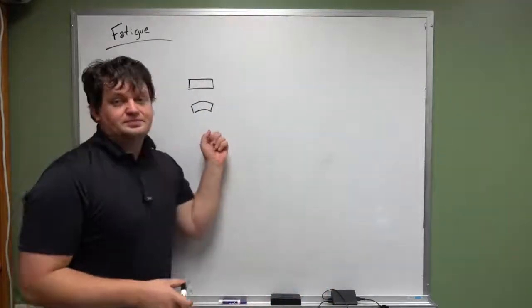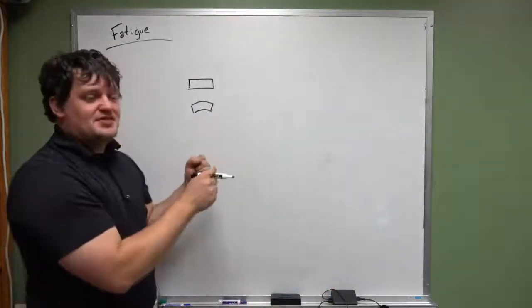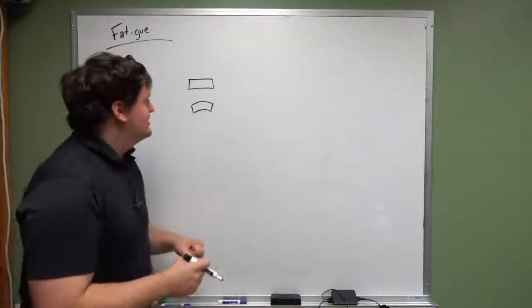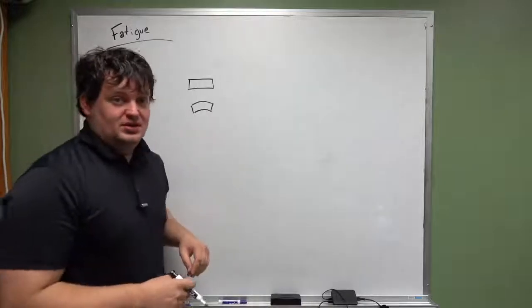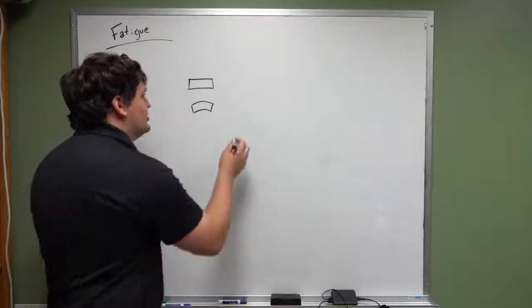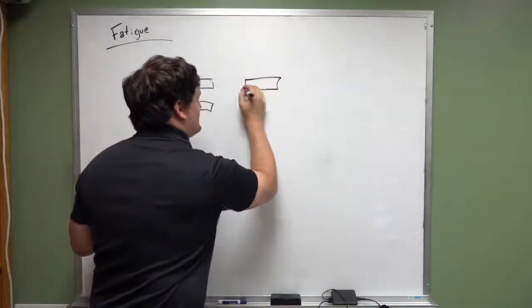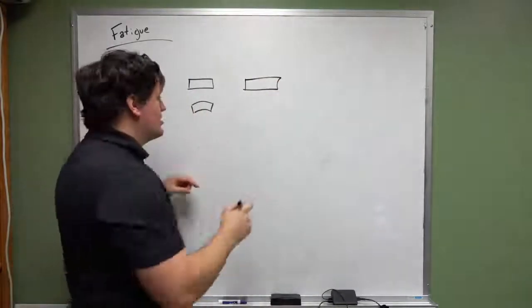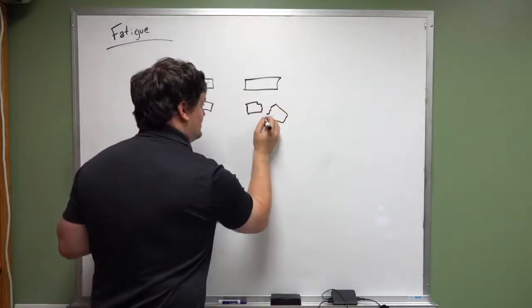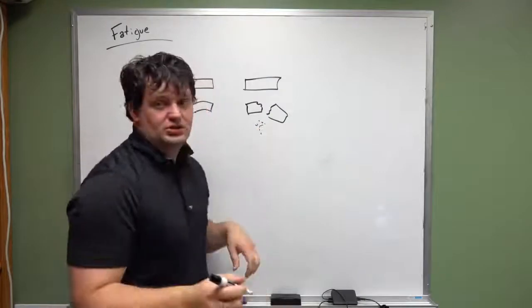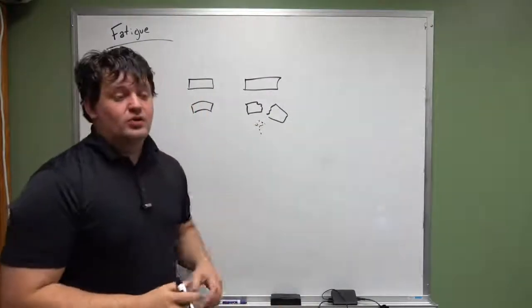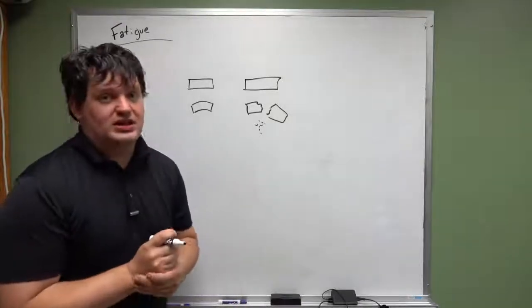So we know that if you just bend this bar, eventually it's going to plastically deform. It's going to stay bent. Okay? This is awesome. Very useful. Static failure, okay? We also know that in more brittle materials, like say this was concrete, you bend this bar far enough, it will absolutely fracture. And you'll end up with concrete dust all over, okay? We've got brittle failure, we have ductile failure. We understand those concepts, that's what we talked about last week.